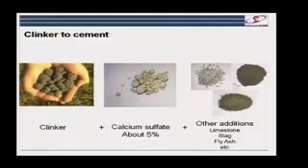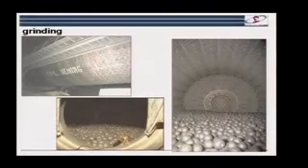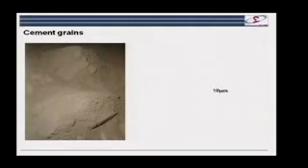So that's our clinker. We've now got to turn it into cement. And to turn it into cement, we make various additions. We always add calcium sulfate for reasons that will become clear later, typically about 5%. And nowadays we also add increasingly amounts of these other things, as I've already explained, because these lower the CO2 emissions: fine limestone, slag, fly ash, etc. This is a ball mill, which is typically used to grind up the cement. You see those are the steel balls that do the grinding. And then we end up with cement.